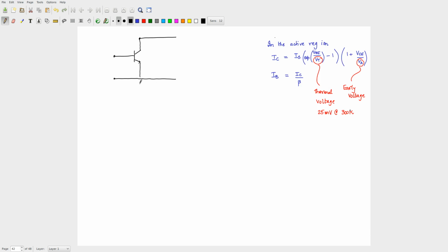I gave this in an exam, right? So this is plus minus VBE, this is IB, this is IC, plus minus VCE, and IE you don't need. For the 2-port network you don't need that. So for the 2-port parameters, this will be V1, this will be V2, that will be I2, and that would be I1. I have just drawn everything as capital letters, but I am not going to rewrite everything. All of these should be incremental quantities. So write the answer in terms of incremental quantities. I have written everything with capital, that is not correct.